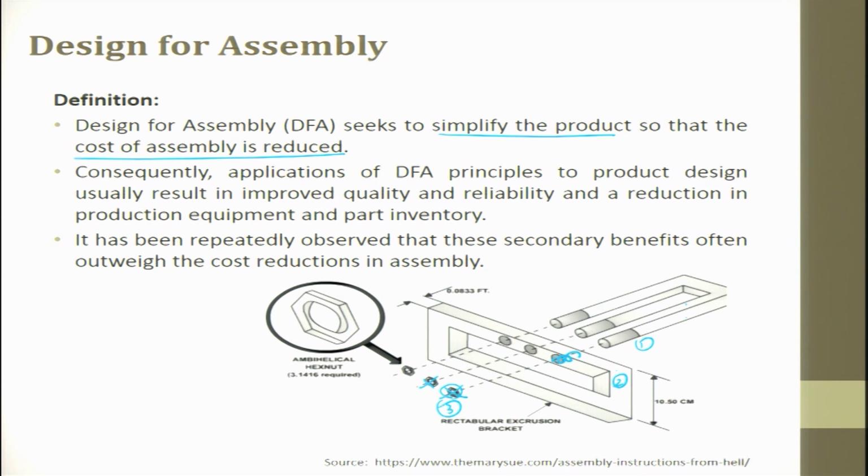So, you have reduced a part and this reduces the failure of the complete product. Okay. So, we can always think of making a thread along inside the hole and try to fix this part with this part directly rather than using a fastener.